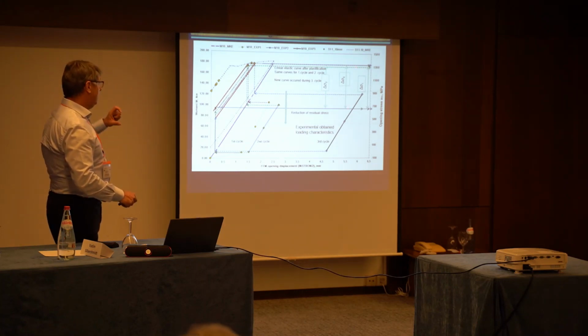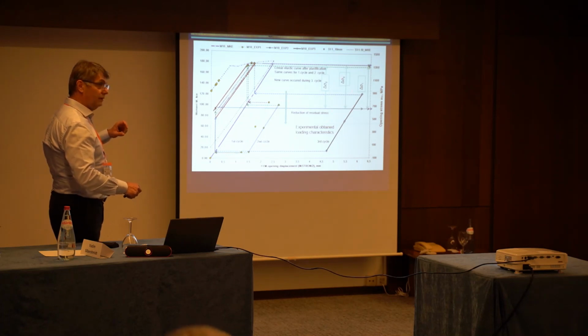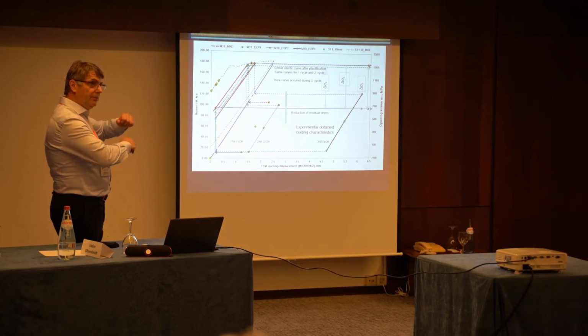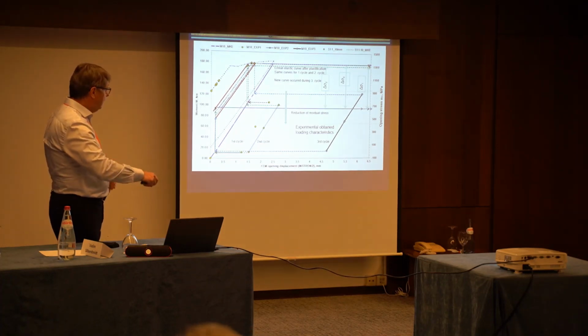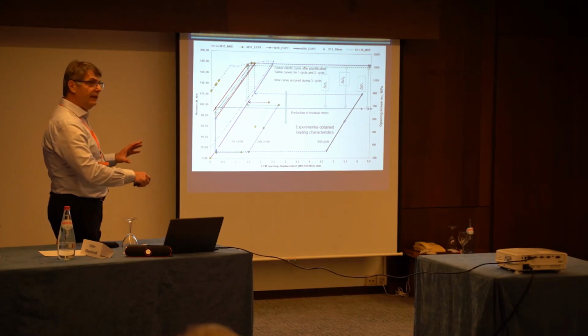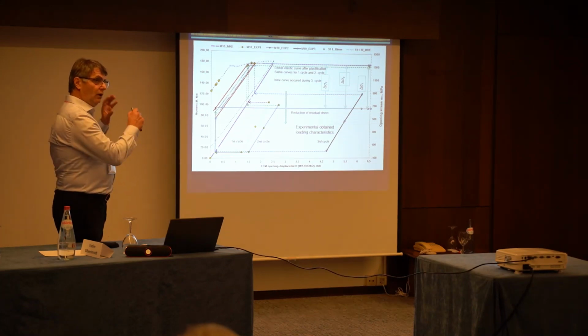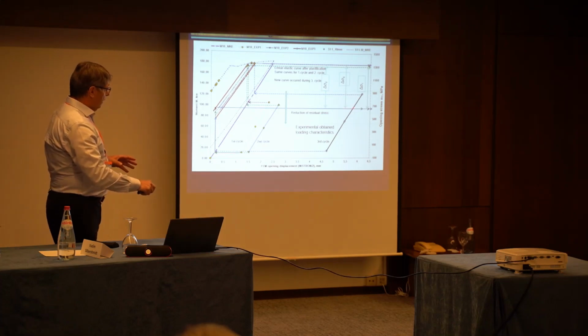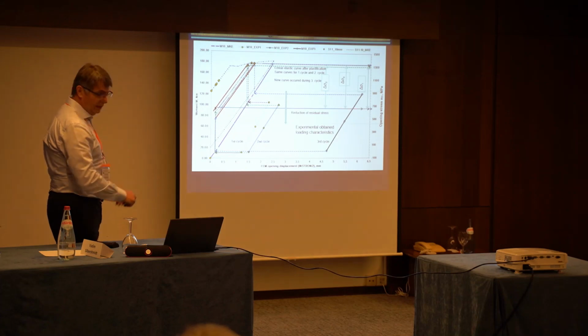When you start the loading with this amplitude, you have this R ratio, and if you stop, you will change it. But if you always use the same, and do not go lower than this or upper than this point, you can say that this is my constant loading amplitude with a ratio, which we can calculate from the ratio between this stress and this upper stress.